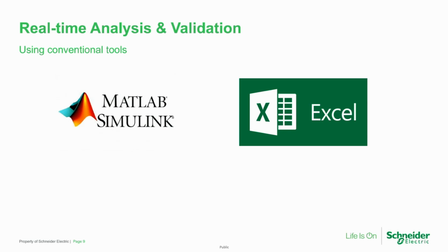To continue the POC, we had to do some real-time analysis and validation. So we used different tools like MATLAB Simulink and an Excel sheet. So basically, it's no longer a CAN stack. We took a simple application, like a business application, let's say, which was running on Simulink, and we built it and simulated it with Simulink. So basically we took some inputs that we put on the board, and we recorded the outputs, and we did that on Simulink, and we did that on the board with the loaded code.